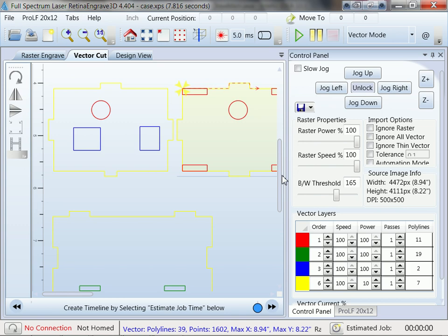Unfortunately, if you make an injection molded plastic mold, you're dealing with about $3,000 for the bottom half and another $3,000 for the top half. So by the time you're done with engineering costs and your mold making, you're probably into the device for a good $6,000 to $10,000. And then you can produce it out of engineering plastic. Engineering plastic per pound costs as much as a gallon of gasoline because it's a petroleum product. So as the cost of gas goes up, the cost of the plastic goes up.